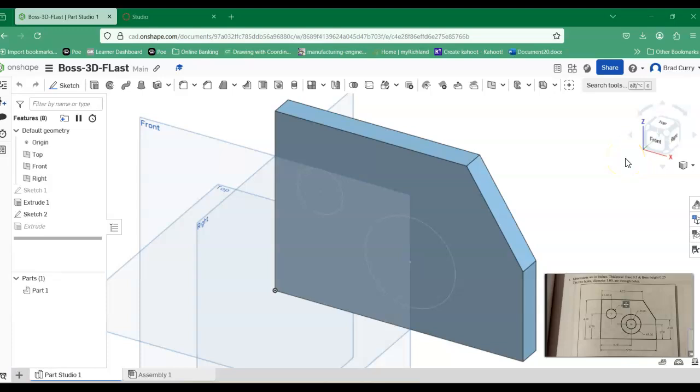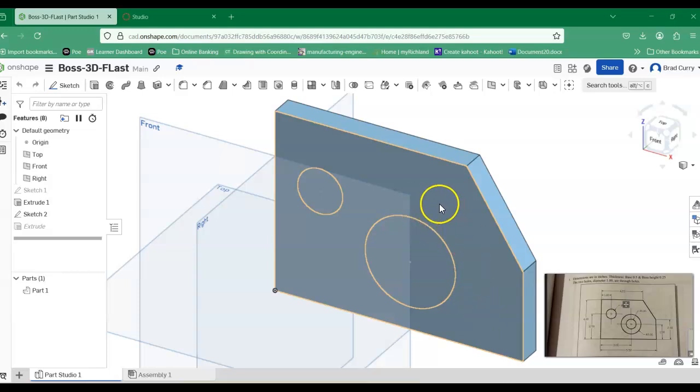All right, we are back here with part two of the video on the boss. As you recall, we last left off with the video where we had created a sketch on this surface, the sketch of the boss and a sketch of the 1-inch diameter. We're going to make this a hole, and extrude this boss out towards us. I'm going to talk about how a sketch gets consumed by the extrusion when you use it. So we'll head right here.